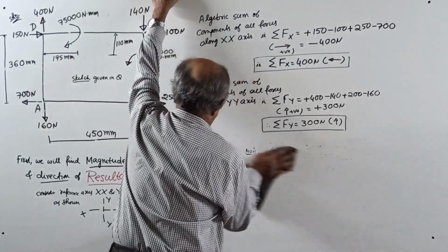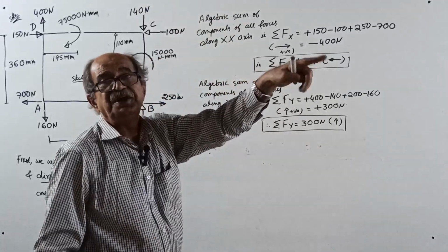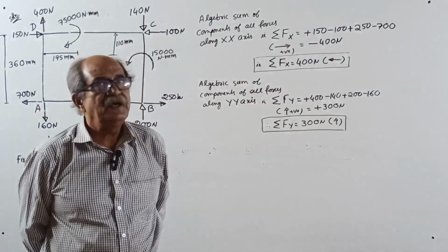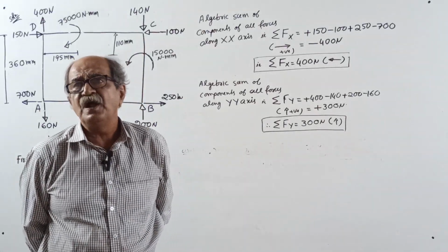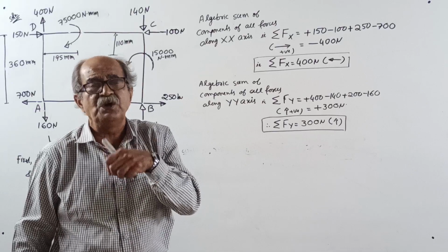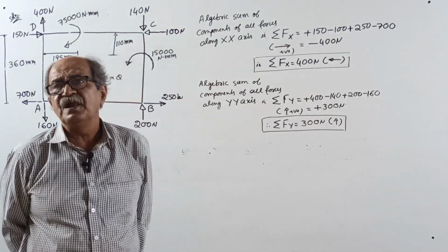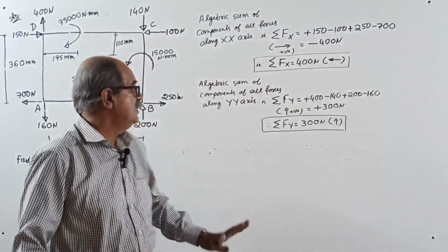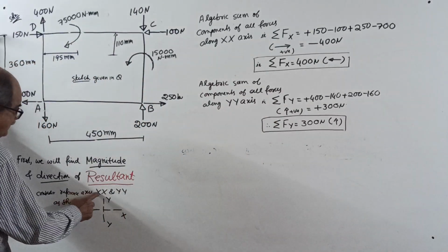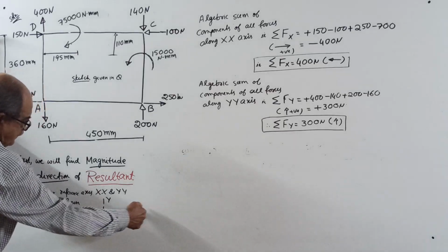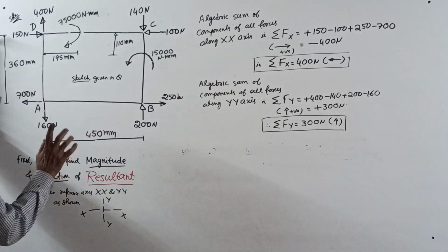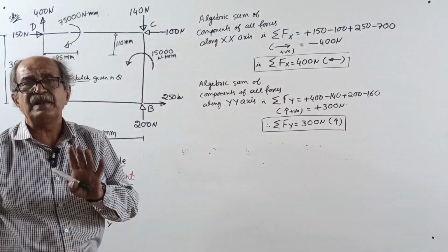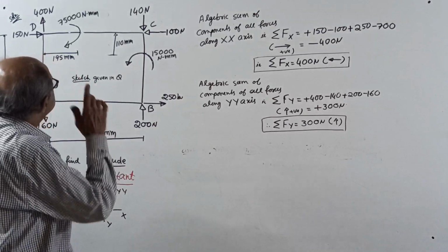Now, one by one. See, go to the procedure sheet. If inclined forces are given, better to resolve them into horizontal and vertical components, or along x-axis and y-axis. I'm telling the procedure for you. So therefore, consider reference axis x-axis and y-axis. This is x-axis, this is y-axis. Write it here. Everybody knows it, still better write. Okay, then further.